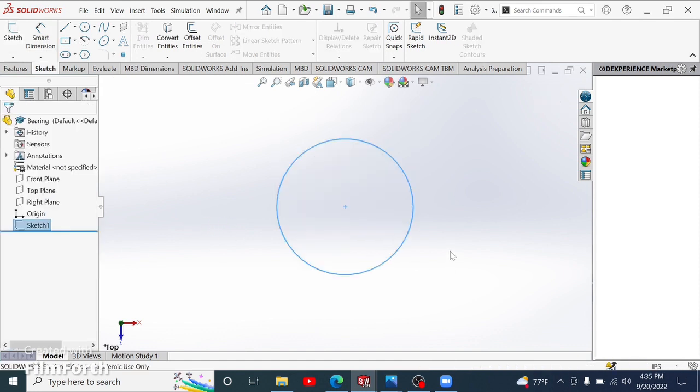Okay. On blueprints, it'll give you a unit. So you can't really tell on the blueprints right here in my book anyways. Most of the times on blueprints, they'll try not to indicate it most of the time. You have to look at it very carefully, and you have to know if it's in inches, millimeters, or centimeters. Sometimes it'll indicate a little icon above here on a square section, or down here on the blueprint. It'll tell you that your unit's going to be in inches, metric, or in centimeters. On my blueprint, it says metric.